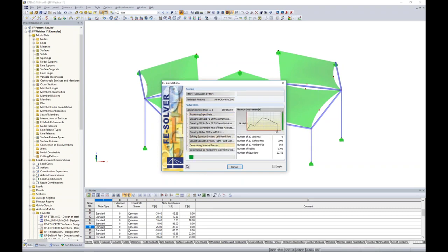Now remember, we lost our form finding results previously because I said, well, I want to include self-weight now. So we're now including self-weight. The program needs to run back through that form finding procedure. Then we're applying the downward load for live load. Now, eventually the program is going to cycle through. You can see the iterations here for max displacement for the different iterations applied, and eventually we'll be presented with our results. So again, we're using just this single load case here to determine where these high tensile forces will be acting on our structure.